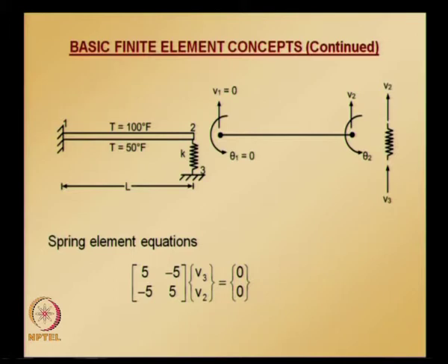The tricky part is where the spring element contribution goes in. To decide that, note that the spring is connecting node 3 and node 2, and at node 2 the common degree of freedom between the spring element and the beam element is the transverse displacement V2. So the spring element goes into rows and columns 5 and 3 of the global equation system.